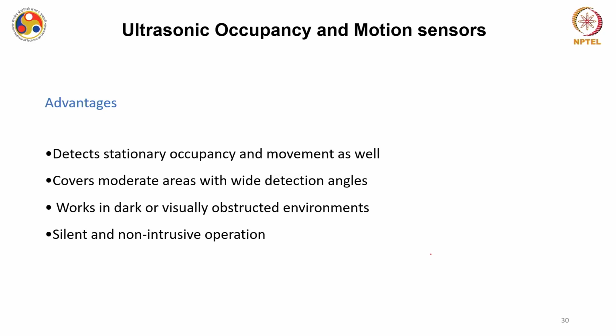Okay, so for stationary occupancy, we have seen that there will be a slight disturbance in the ultrasonic wave, while for movement you have a change in the frequency pattern. Then it covers a moderate area with wide detection angles, as the transmission we have seen is diffused, or the reflection is diffused, there is a large angle of reflection, and that's why the detection angles for this kind of device are very large.